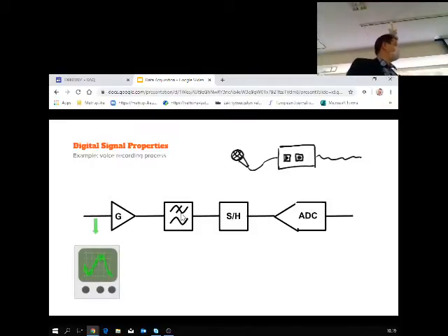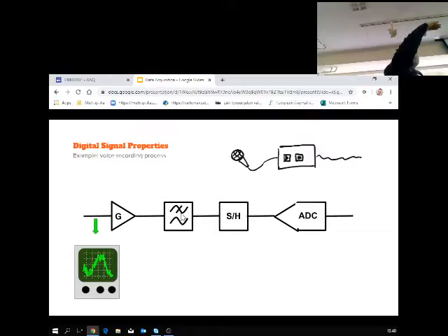Basically we start with the small analog signal, say tens of millivolts, maybe hundreds of millivolts. In principle, these dynamic microphones are designed so that in normal usage, the signal is between plus and minus 200 millivolts. That's small compared to the A to D converter conversion range, which is usually volts.